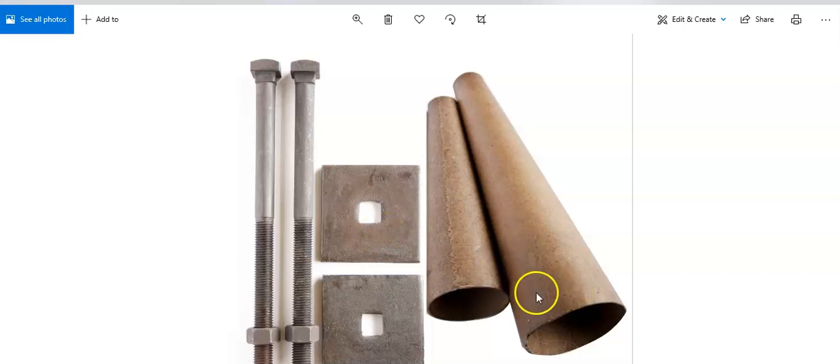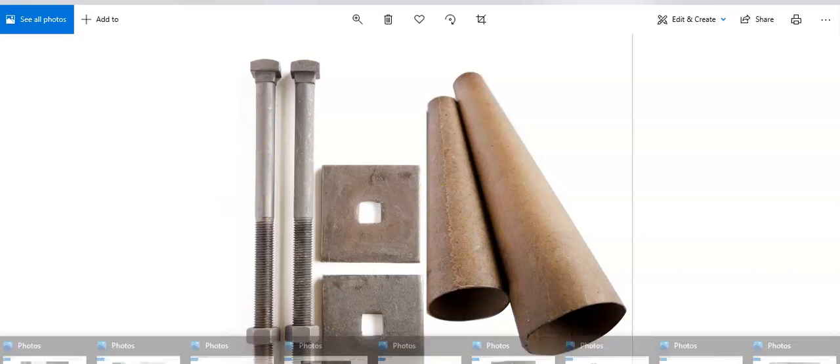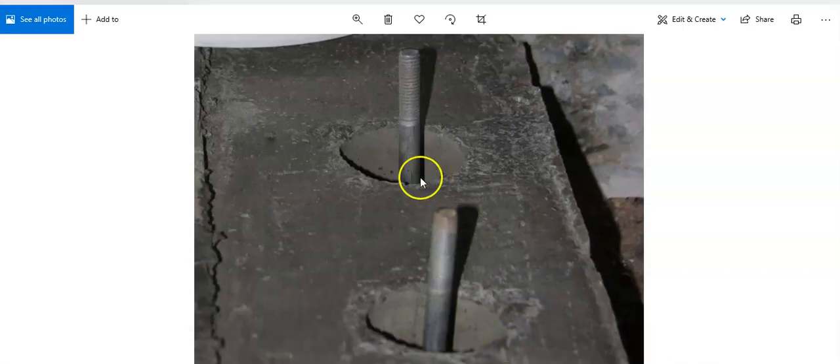How about this? These are the cones, which are part of these items, and in the end they give us flexibility, like we see in this picture. Once the cones are fixed and taken out afterwards, if there is any error in the setting out, we have flexibility to move the bolts in 360 degrees to get into the exact position.